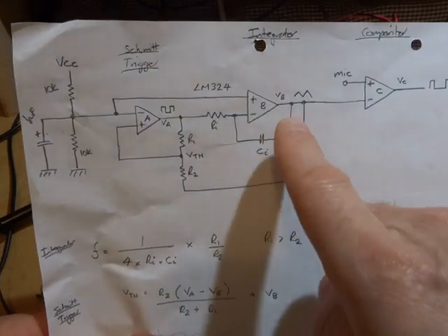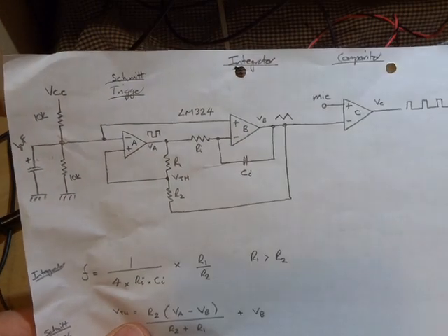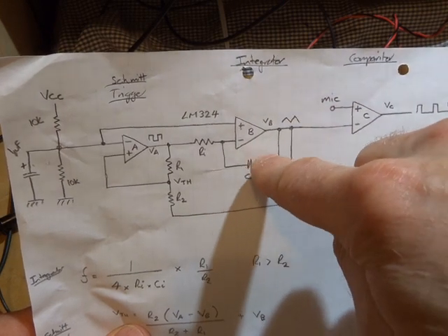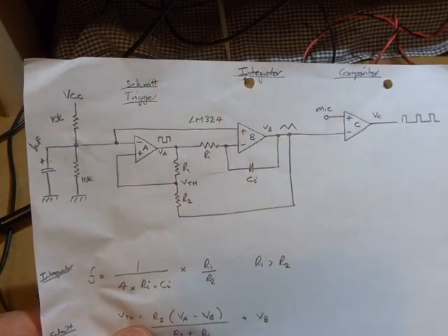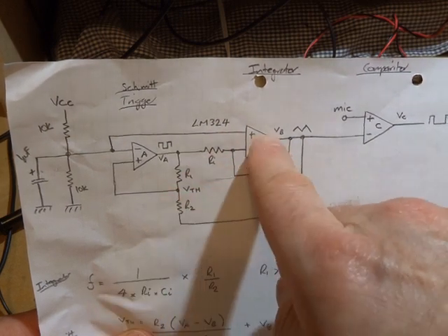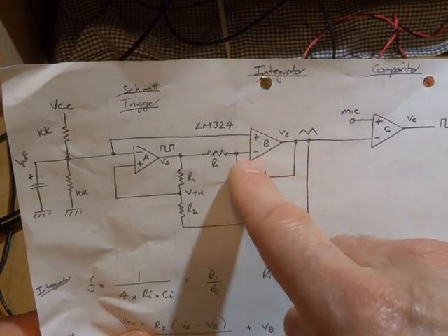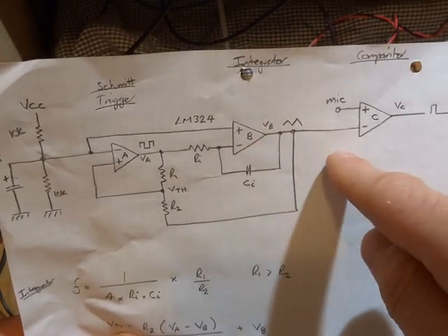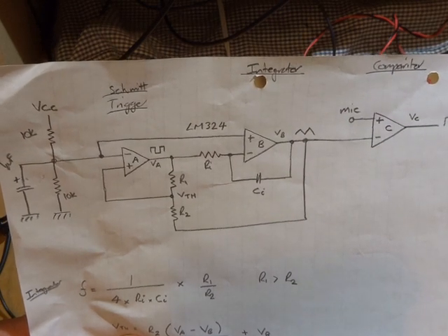While I managed to produce an output waveform, it really wasn't clean enough to be used. It didn't have nice straight sides. It had some artifacts in there which I just really couldn't get out. I put that down to the LM324 not really being a high-speed device, and the slew rate just wasn't going to be high enough for 70 kilohertz. If I dropped the frequency down to a couple of kilohertz, it got extremely good, but up at 70 kilohertz, it just wasn't cutting the mustard.